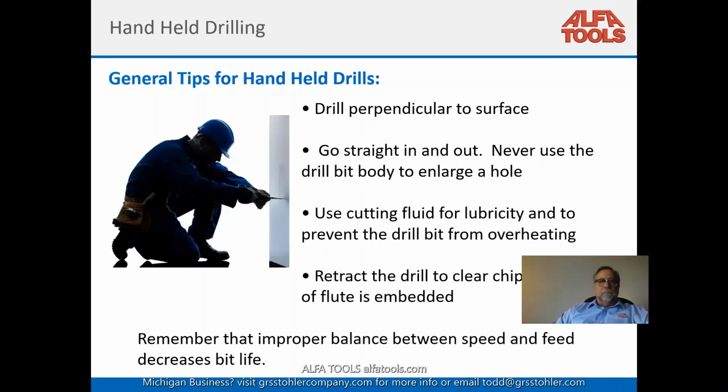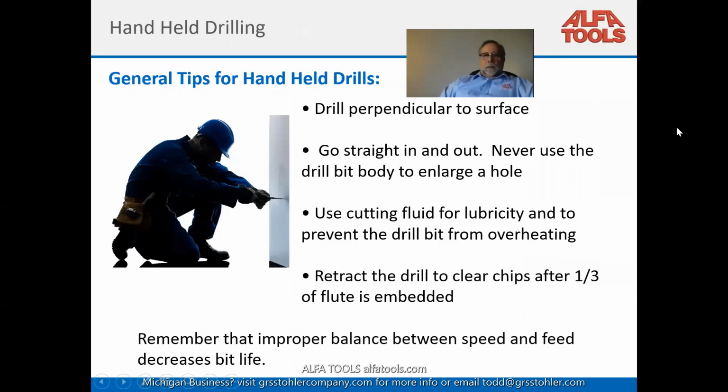What else do we have? Okay, so a little bit of handheld drilling tips. This is the easy one. Go straight in, straight in and out. Don't twist the drill around because you need a bigger hole. That's the reamer's job. I mean, we've all done it. You know, let me get in there, I can get this bolt through here. Use cutting fluid if you have some. Even if it's water for cooling, a little bit of oil, anything to help with lubricity. Any kind of fluid for cooling and lubricity will give you better tool life.